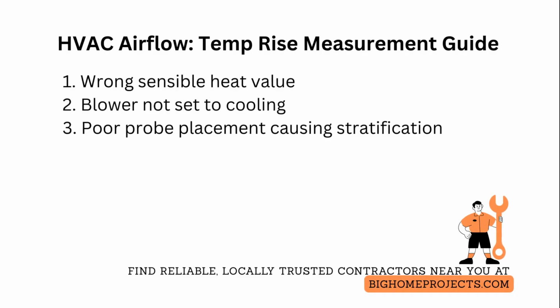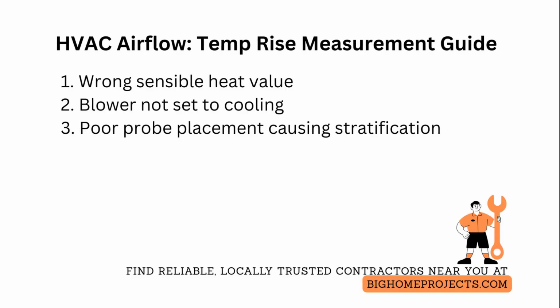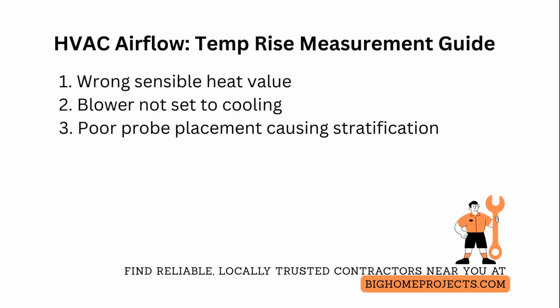One of the typical issues is poor probe placement and temperature stratification causing noisy or biased readings. Fix this by placing probes away from register edges, maintaining 3 duct diameters of straight run when possible, averaging multiple readings, and documenting probe locations.